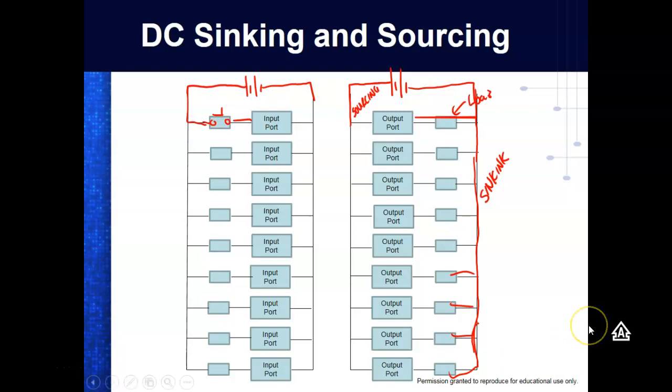Okay. So who runs this wire right here? Yeah, you do. You have to run this wire to all your input devices. The book doesn't do a good job of that. It throws that syncing and sourcing out there, but it doesn't tell you that, and that's very, very important.